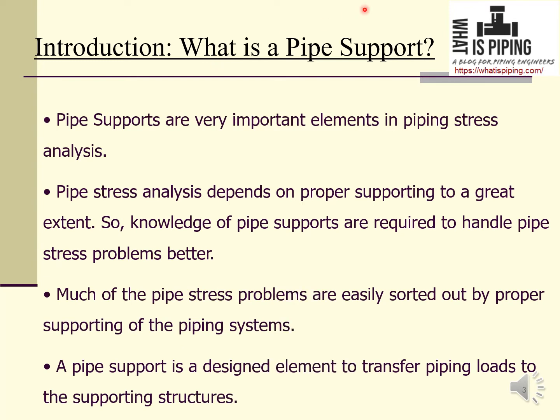Now, what is a pipe support? Pipe supports are very important elements in piping stress analysis. Pipe stress analysis depends on proper supporting to a great extent. So, knowledge of pipe supports is required to handle pipe stress problems better. Much of the pipe stress problems are easily sorted out by proper supporting of the piping systems.